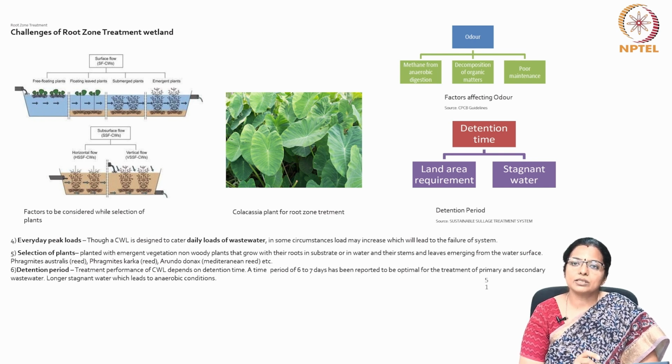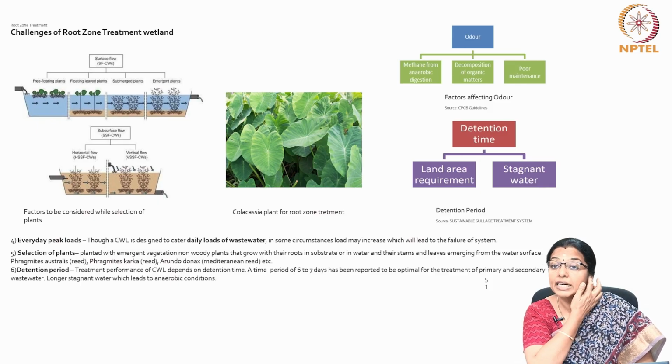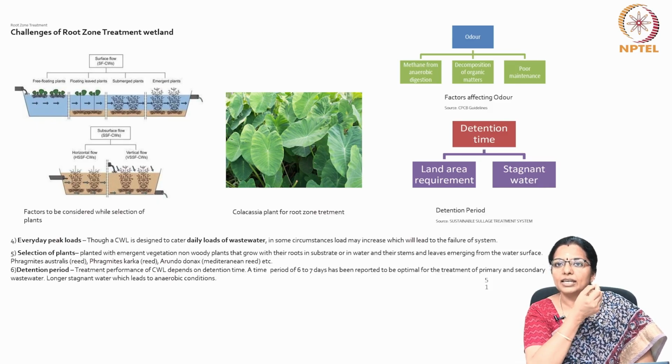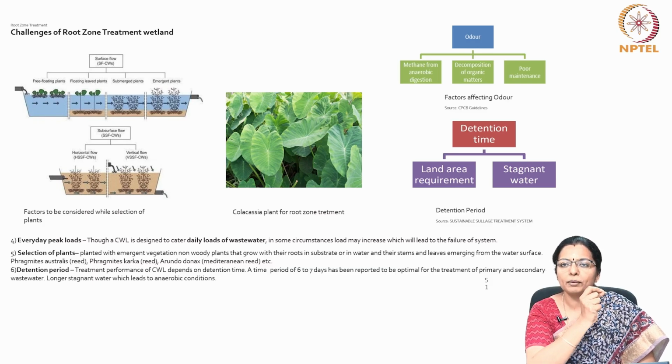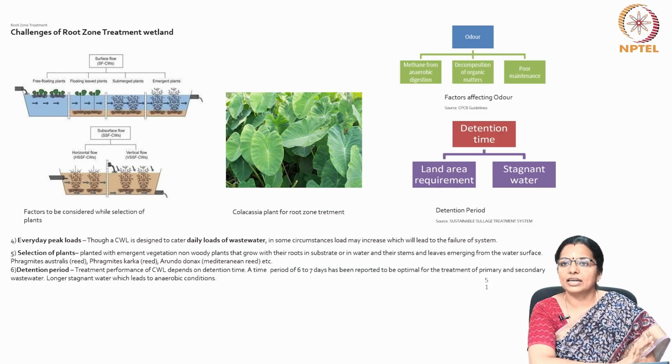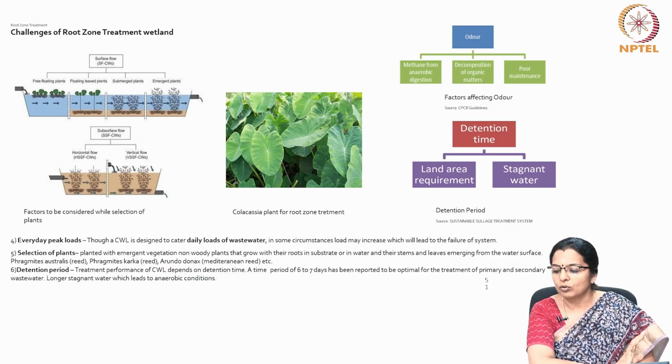Treatment performance depends on the detention time. A time period of 6 to 7 days has been reported to be optimal for the treatment of primary and secondary wastewater. Longer stagnant water can lead to anaerobic conditions and can give out smell.